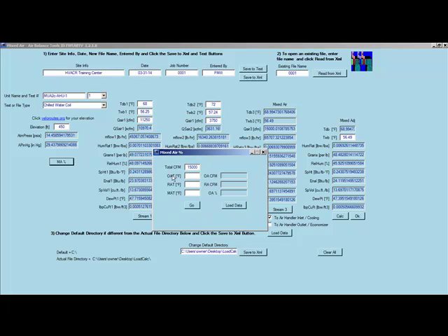Our outside air, or in this case our makeup air, is 68 degrees. Our return air is 72 degrees. And our mixed air is 68.99. In this case, when you're using this mixed air tool, you want to carry it to the ones. So let's go ahead and carry this to 69. And so that gives us 11,250 coming from the makeup air unit, 3,750. So 75% of this air is coming from the makeup air unit.